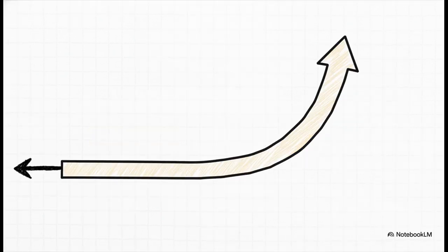Well, if you said high order, you nailed it. It's high order because that flat dead start is the definitive, undeniable signature of multiple lags stacked in series. Remember, a true first-order process, no matter how gigantic or slow the tank is, will always start responding immediately at its maximum rate of change. So, dead time? Dead time equals high order.